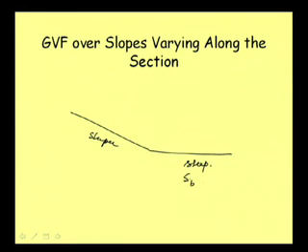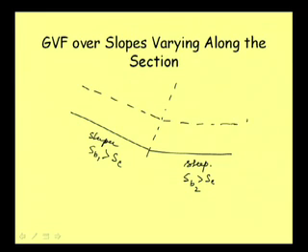So SB is greater than SC, of course, SB2, and SB1 is also greater than SC, and let me draw this line here and say critical depth line. So this is CDL, and then SB1 is greater than SB2. So far as normal depth is concerned, here the normal depth will be this one, suppose NDL. Okay, this is my yn1.